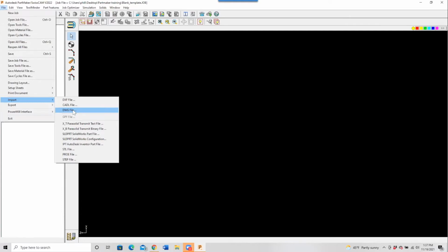So if you are receiving DWG files from your customers, just request that they send the DXF file instead. That's the actual drawing in AutoCAD, which will be scaled 1:1. It just saves you a lot of time and effort before you have to start programming on a wireframe part. Okay. So again, DWG files, I really don't like them just because of all the work I need to do to them to get them ready for programming.